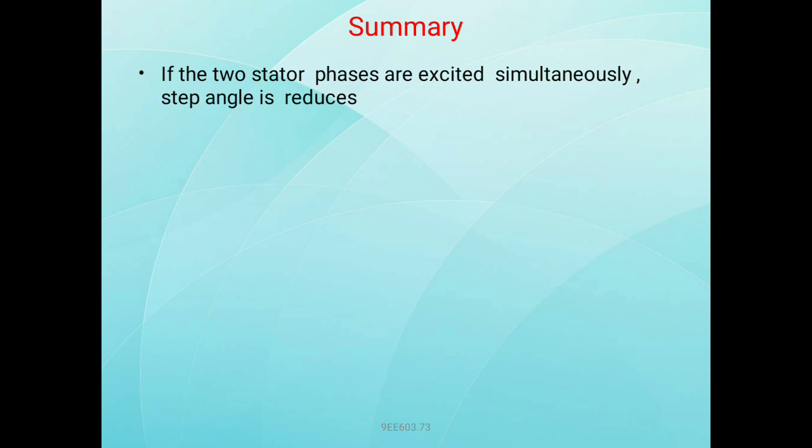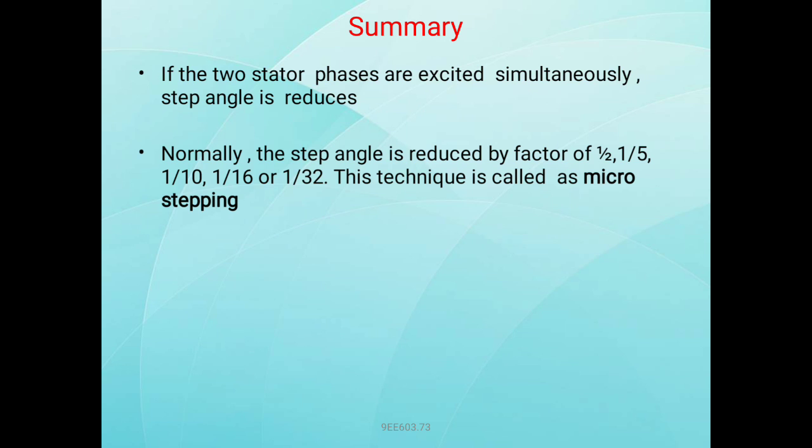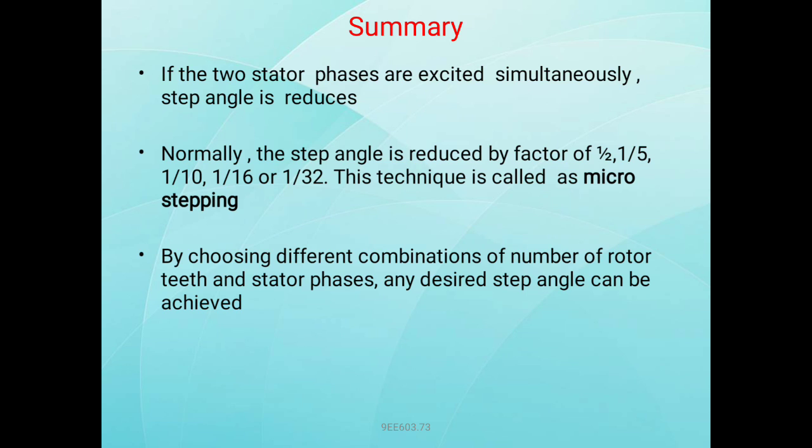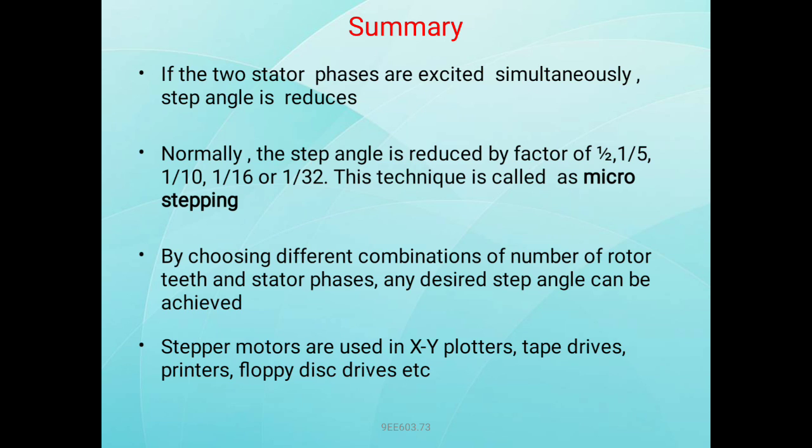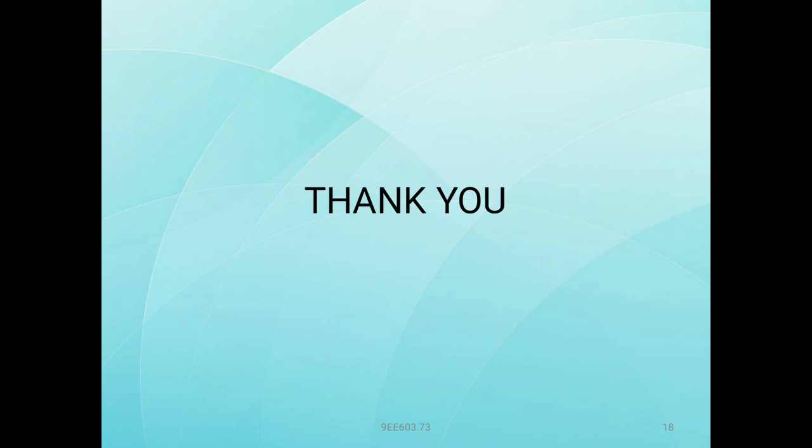When two stator phases are excited simultaneously, the step angle is reduced. Normally, the step angle is reduced by a factor of 1 by 2, 1 by 5, 1 by 10, 1 by 16, 1 by 32. This technique is called micro stepping. By choosing different combinations of number of rotor teeth and stator phases, any desired step angle can be achieved. Stepper motors are used in XY plotters, tape drives, printers, floppy disk drives, etc. Thank you.